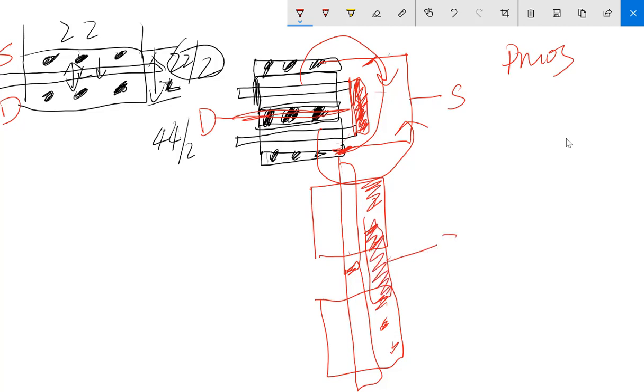And this is the source, right? You rotate it in that way, just imagine you can break it in the middle. After you break it, you rotate it and combine like that. And that's your drain, and the drain is being shorted as well. Why is it being shorted? Because originally they were just one node over here.